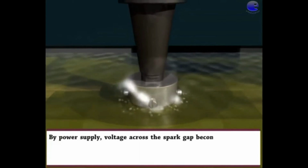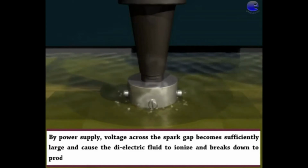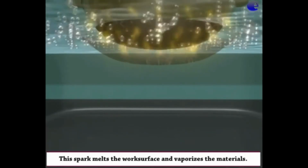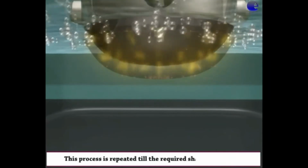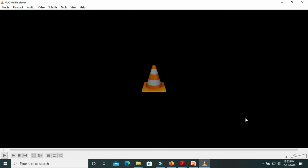By the power supply, the voltage across the spark gap becomes sufficiently large and causes the dielectric fluid to ionize and break down to produce a dielectric spark between tool and workpiece. For that purpose, maintaining the gap between the electrode and workpiece is a very important factor. This spark melts the work surface and vaporizes the material. So due to the high temperature between the electrode and workpiece, the material is melted and removed from the workpiece surface.